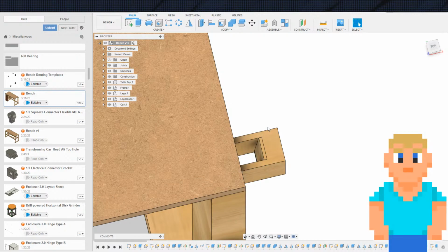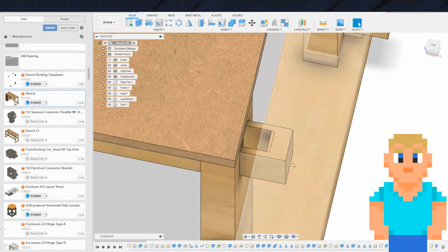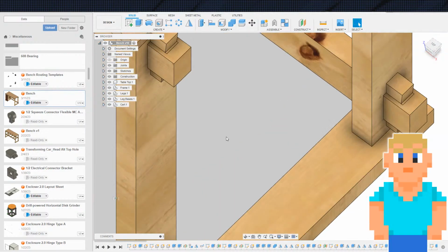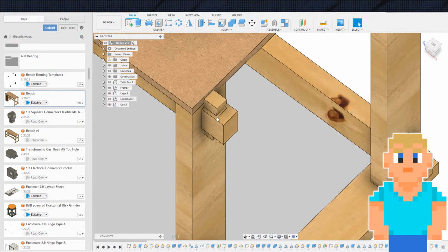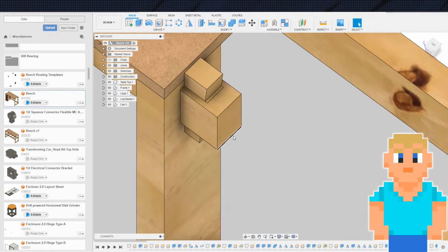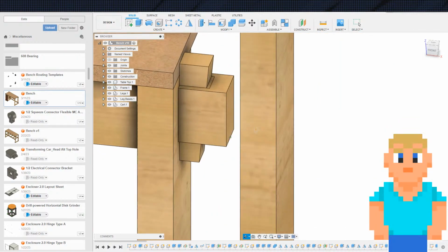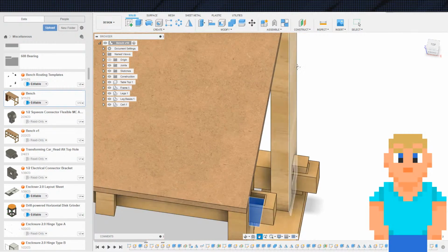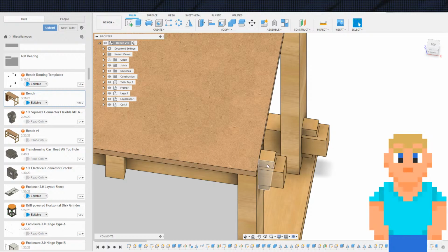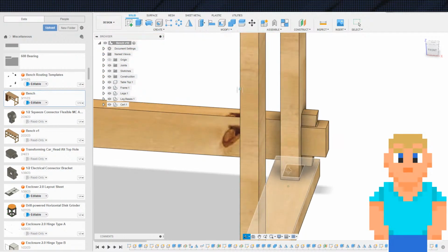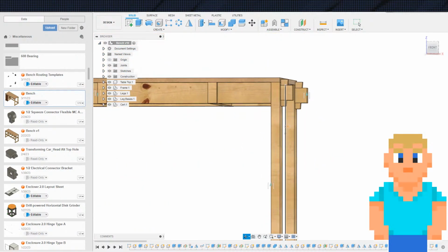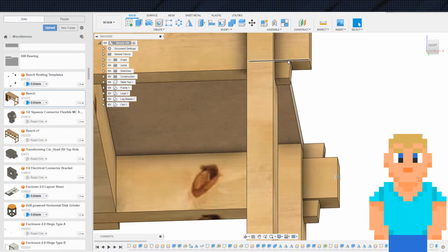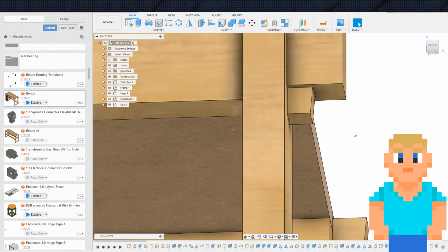So I can put a tapered insert in here in order to provide a taper for the tusk to go against, because you need two tapered surfaces in order for it to pull itself together. That's the point. So instead of trying to cut this taper myself, I was going to just insert a taper piece. When the tenon gets banged down, this will just get banged further down into the bottom here, which again is not open for that piece. So that was the game plan.